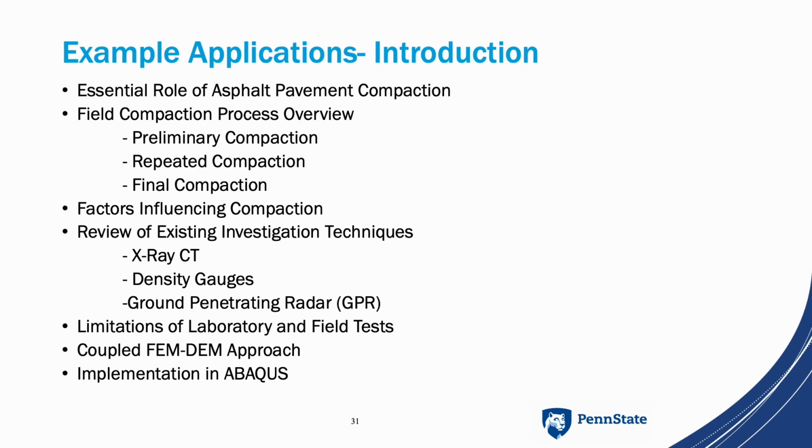For the last part, ground penetrating radar, also called GPR, is a non-destructive testing tool that employs radar pulses to detect and picture conditions beneath the ground surface. It is high speed, uninterrupted, and rich in pavement information, regarded as one of the most promising tools. But the application of GPR to forecast the in-place density of asphalt mixture is still in its early stage.